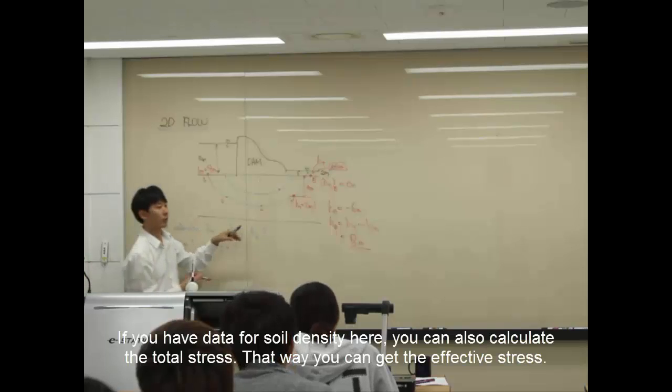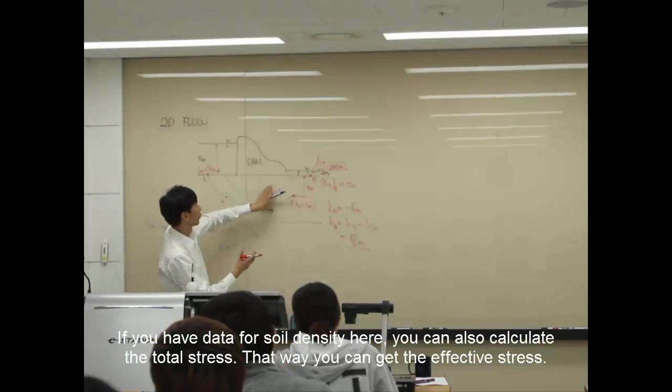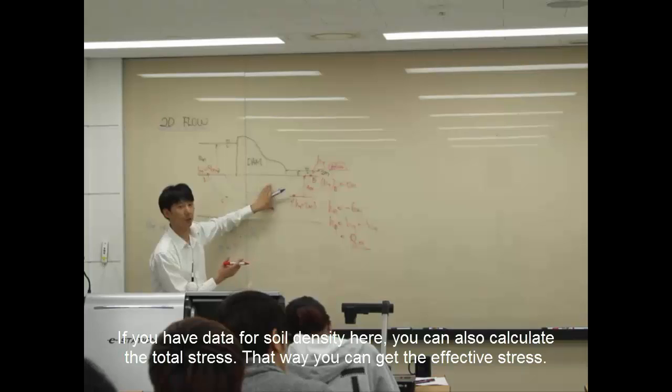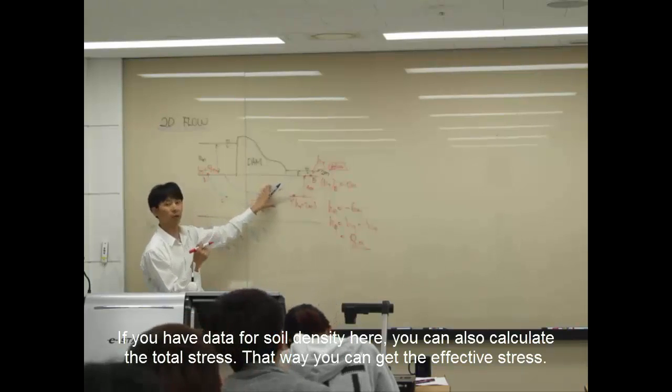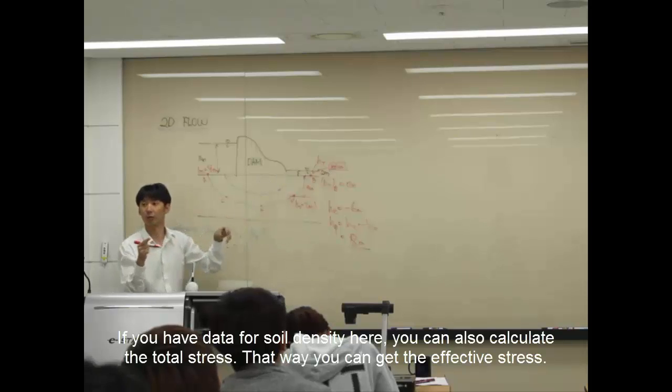And if you have the data for the soil density here, then you can also calculate the total stress. So that way you can calculate the effective stress.